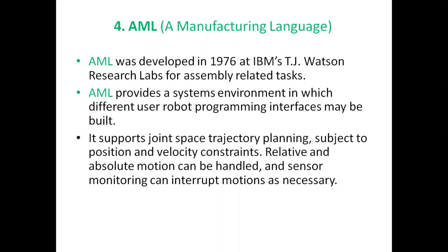It provides a system environment in which different user robot programming interfaces may be built. It supports joint space trajectory planning subject to position and velocity constraints. We'll have relative and absolute motions which can be handled, and sensor monitoring which can interrupt motions as necessary.